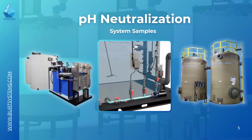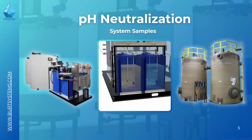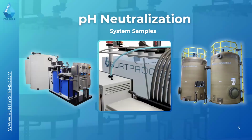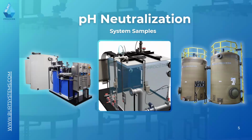It is specifically designed to handle stronger waste streams by using things like recirculation pumps, which use the waste as a carrier medium to allow you to do treatment, as well as having either an integral equalization package or an integral batch design while having to maintain flow into your system.